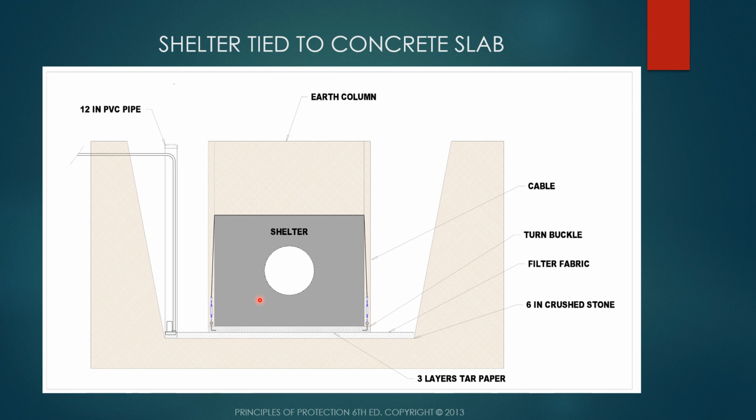Every shelter has got to be below the water table at some point, and it's hard to get culverts to be watertight. So what you want to do in every shelter, I don't care what it's made of, have some way of lowering this water table. You can put a 12-inch PVC pipe, put a lift pump down here, and be able to pump that out maybe 100, 200 feet away and lower the water table so you can repair the leak.